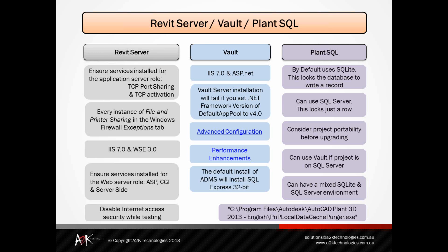If you are using the SQL Server environment and you have any sort of connection issues or any sort of issue at all, you can see at the last point there is actually a file called the PNP local data cache purger.exe, and I would strongly recommend, if you're having any issues at all in the SQL Server environment, that you run that exe.